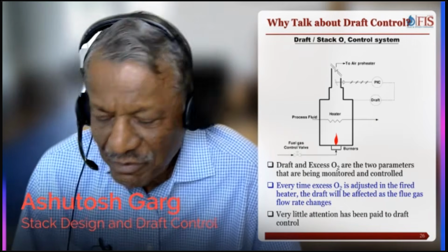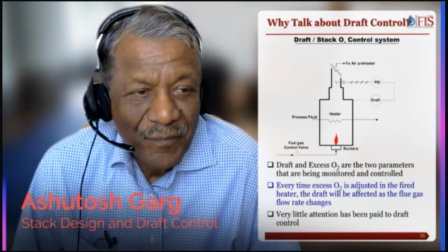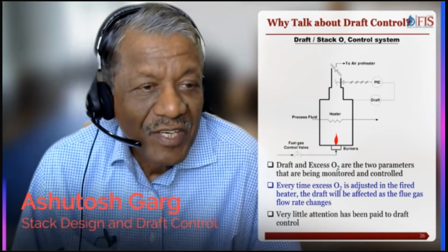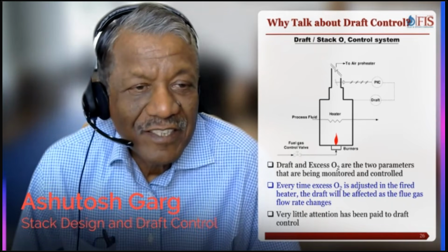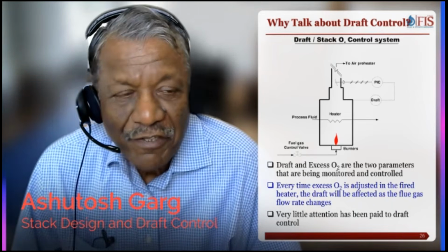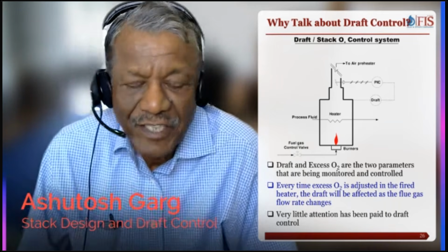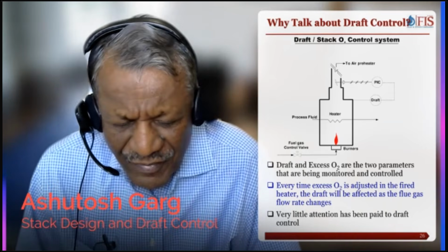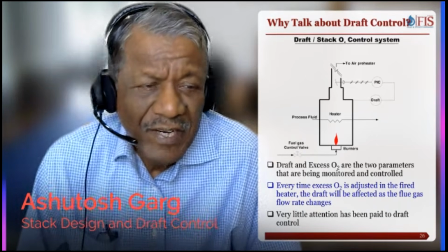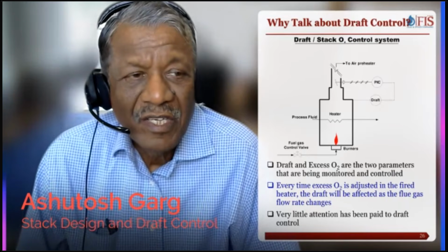But draft became like a step brother or step sister of oxygen, and nobody took care of the draft because a draft meter costs only $100. Maybe there was not too much money to be made. As a result, we have been doing surveys of fired heaters for the last 30 years, and we find draft is the most neglected parameter in fired heaters.